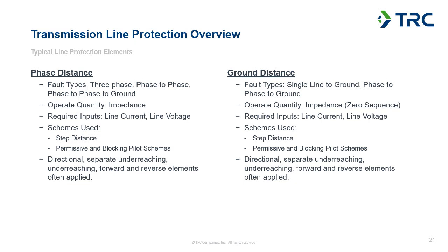is the impedance I'm seeing associated with a fault, which would typically be a lower impedance magnitude and an angle somewhere near the line impedance angle, or is it a normal operating scenario where it's just load, which would have a higher measured impedance associated with load current, and typically would be more resistive than inductive as far as the load angle goes. So we're going to split that, like a lot of our protection, into two different types.